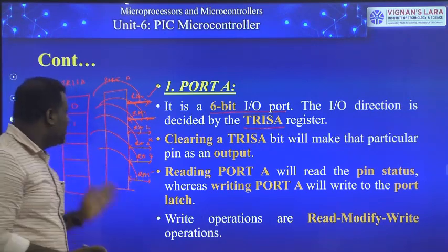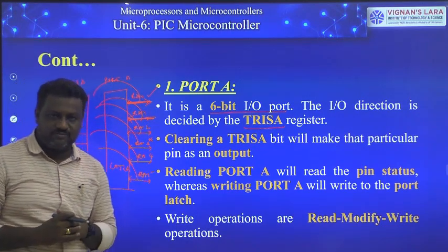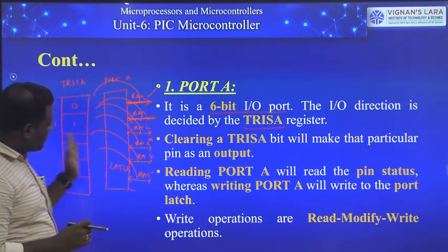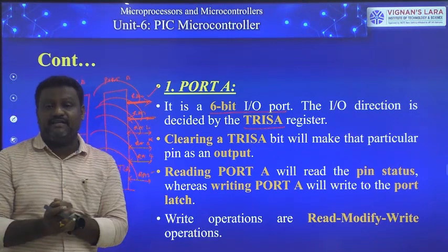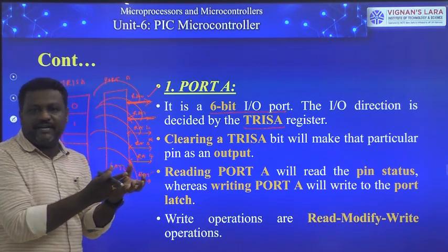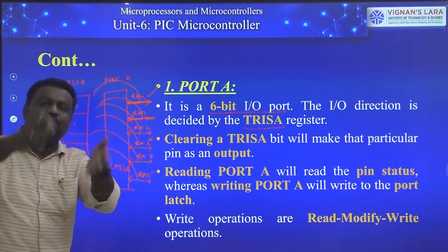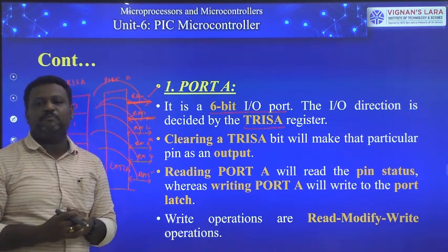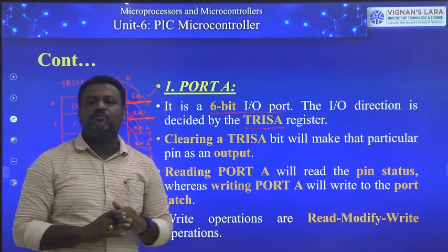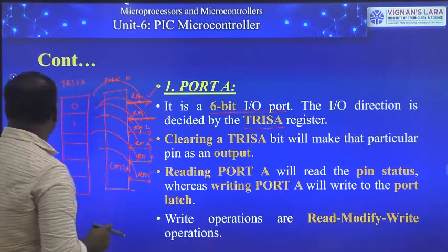But if we are writing something, we are writing the information onto the port latch. That's the meaning of this second point. And the third and last point is that write operations are always read-modify-write. That means first you have to read the information from the pins of this port. Later you have to modify it because we are going to do a write operation. Only after modification can we write the information into the latch of the corresponding port. That's why we say that the write operation of this particular port is read, modify, write. That is the meaning of these points.